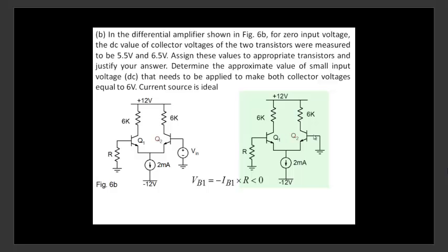So if you want the differential pair to remain balanced, what you should do is, if you have a signal here and it has a certain R, go ahead and put the same value of R here also. So the differential pair will remain balanced in the sense IC1 and IC2 will remain the same. All right. And then whatever is the signal here, then of course it goes through and gets amplified.